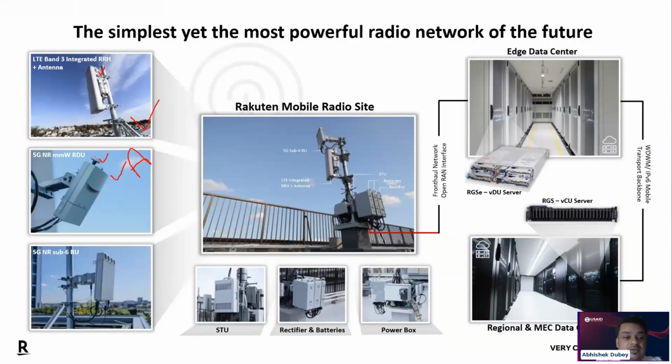You are installing this, and this is a sub-6 frequency RU. This must be an n78 or n77 band, which you have installed here. Again, this is 5G but a different band, and the connectors or clamps can be different with different radio bands or different antennas.